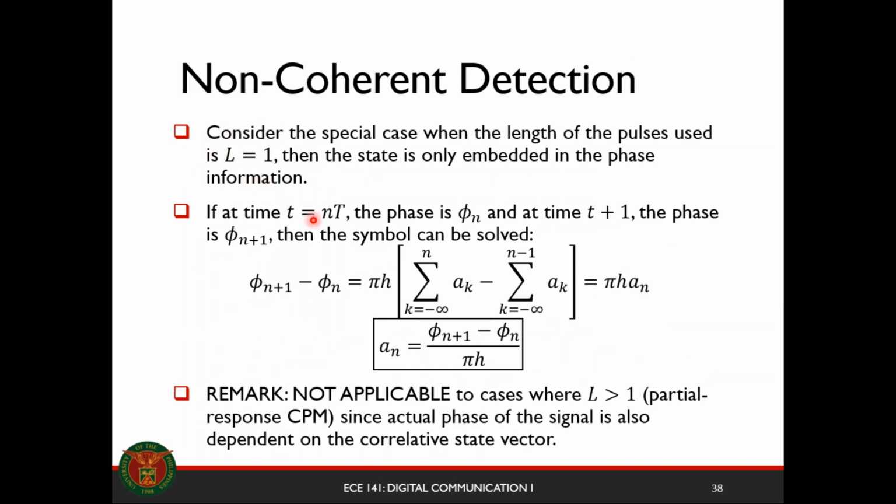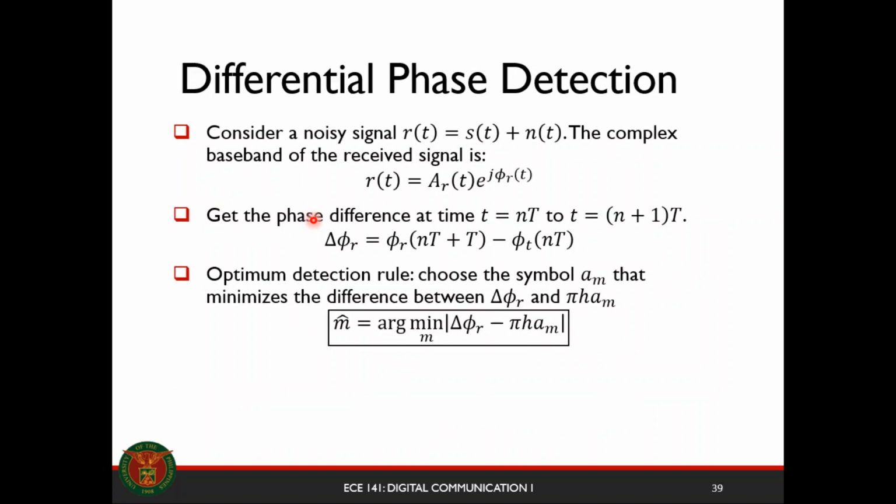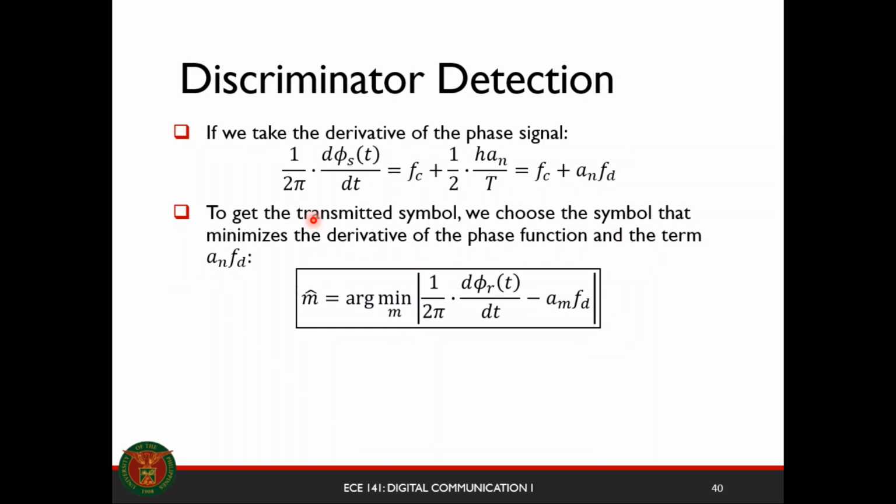And this is an advantage of CPM over your memoryless digital modulation actually. That timing synchronization is already inherent and you just need to track the phase of your CPM signal. Right? And in this case, it's not a CPM signal, it's just a CPFSK signal.